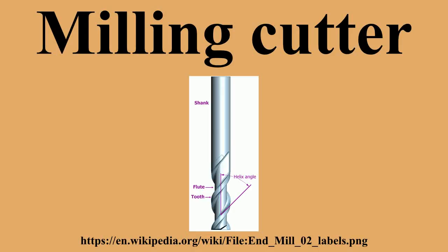Cutter location. Cutter location is the topic of where to locate the cutter in order to achieve the desired contour of the workpiece, given that the cutter's size is non-zero. The most common example is cutter radius compensation for end mills, where the centerline of the tool will be offset from the target position by a vector whose distance is equal to the cutter's radius and whose direction is governed by the left-right climb-conventional up-down distinction.